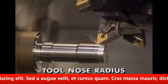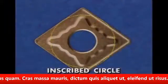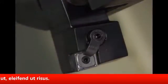The tool nose radius helps determine insert strength as well as workpiece surface finish. Insert size is designated by its inscribed circle, and the inscribed circle size of the insert must match the pocket size of the tool holder.